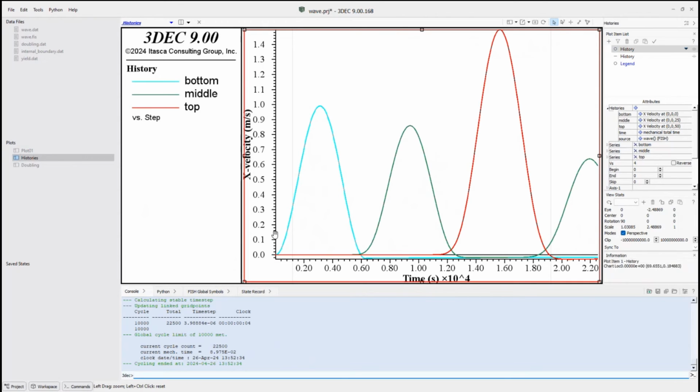Okay, so it takes longer, but you can see that it's actually working. So here's the input wave with an amplitude of 1. Here it is halfway up with an amplitude of roughly 0.9. Here's the reflection off the top. Remember, with no damping, it has an amplitude of 2. Now we're at about 1.5. Here it is coming back down again. The amplitude's at about 0.6. So you can see the Rayleigh damping is taking energy out of the system.